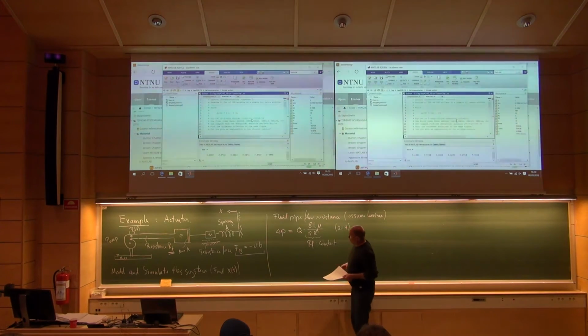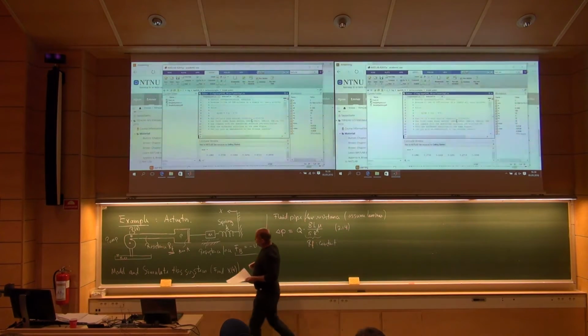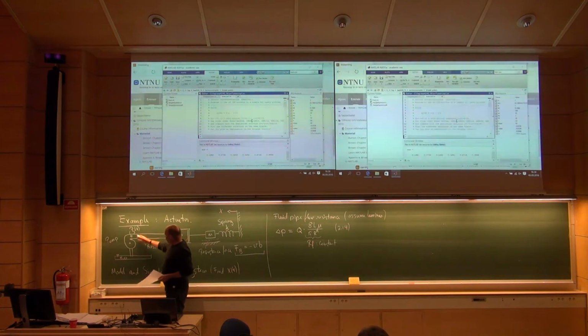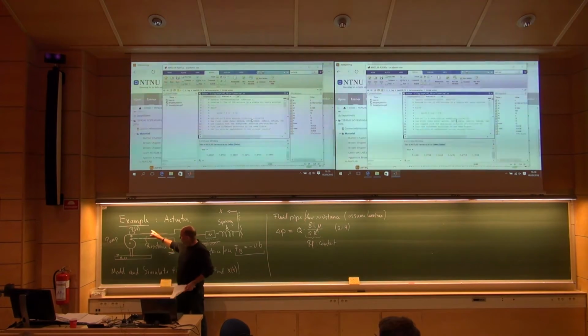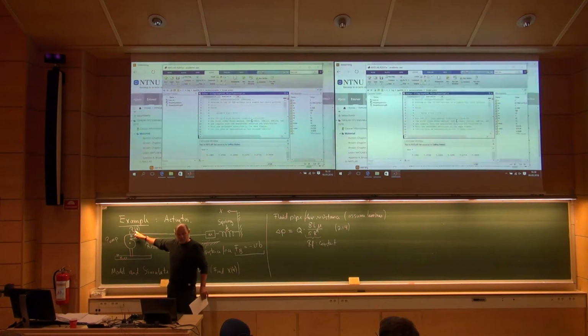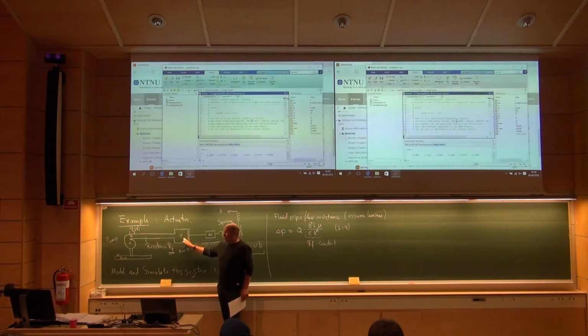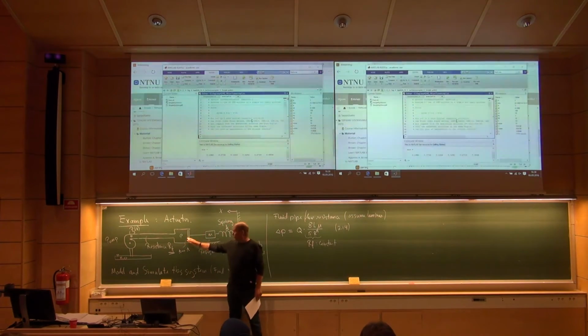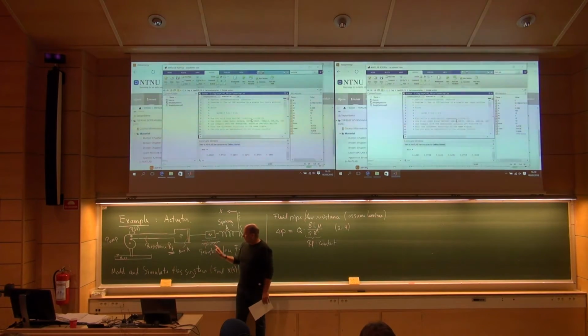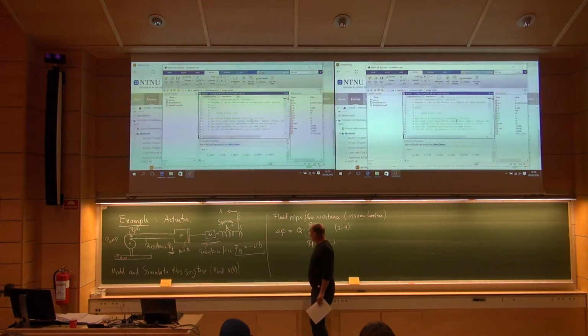Okay, that was the pressure drop. So if the flow is moving to the right here, we know P_S as an input. Then we know the pressure inside this piston here, the big cylinder. And then we can get a force acting on this area, the pressure times area, and we know the force acting on the mass. So now we are getting somewhere.